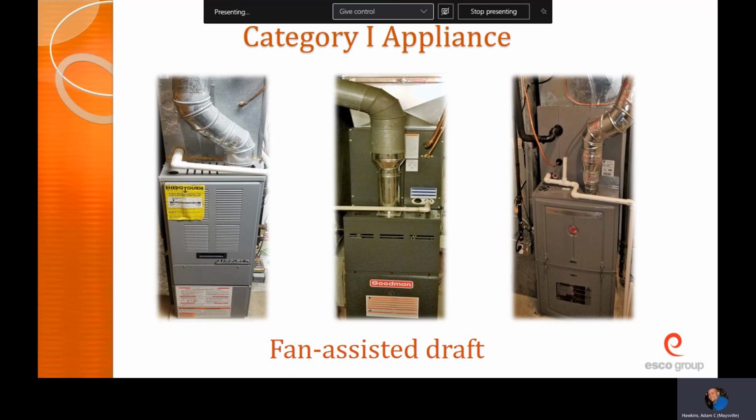Furnace and AC coil setup is usually positive, whereas a heat pump air handler is negative pressure on the coil. So that coil is having air drawn through it versus on a furnace setup like this one, you're actually forcing air through it. It may not seem like a big difference, and it's really not, but it does affect some of the ways that you install it and some of the ways that the system's going to react.